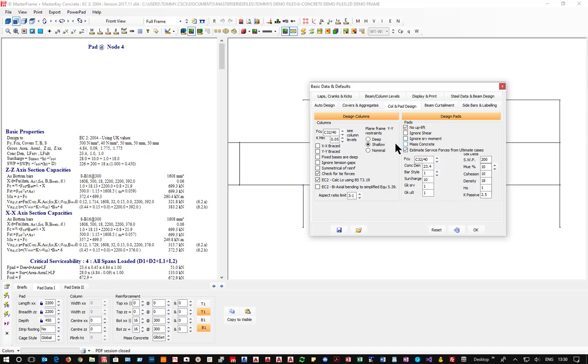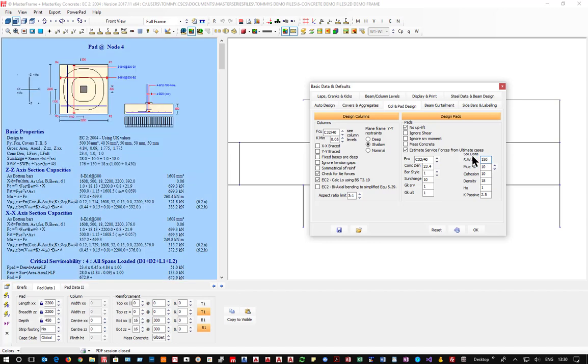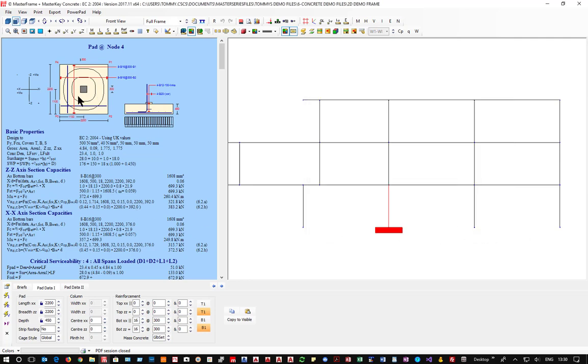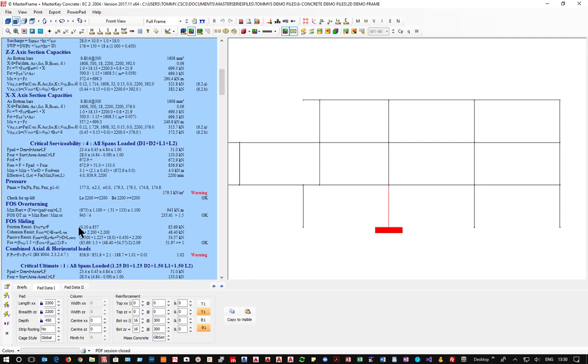That's better. We're going to use C32/40 concrete. We're going to use a 10 kilonewton surcharge from soil and whatever on the pad, and we're going to work with a safe working pressure of 200. So let's reduce that down to 150. Obviously everything changes, and we also have a density and a height of bearing of the soil. Look, we now need to make this work.